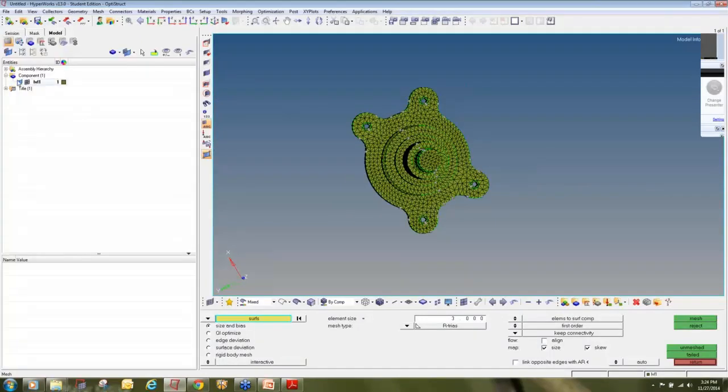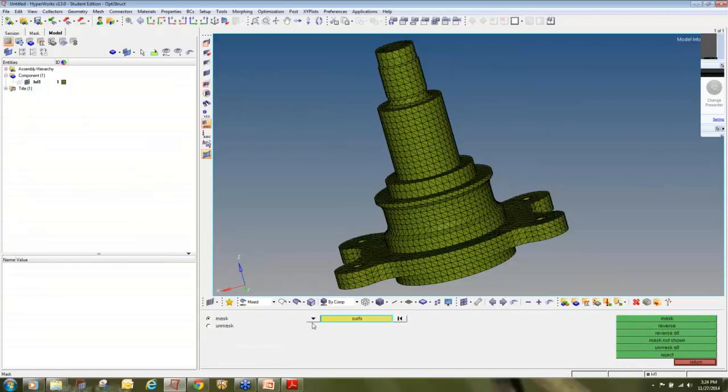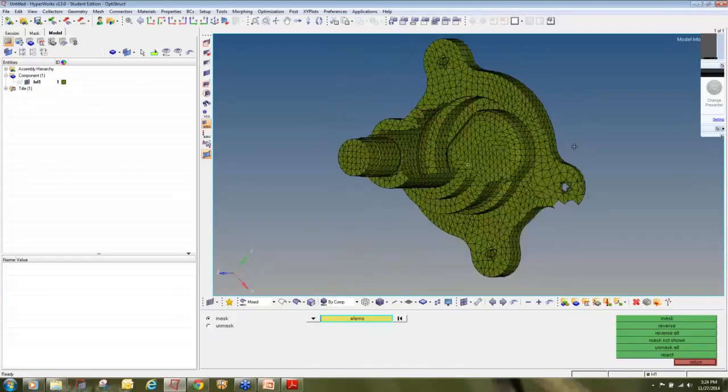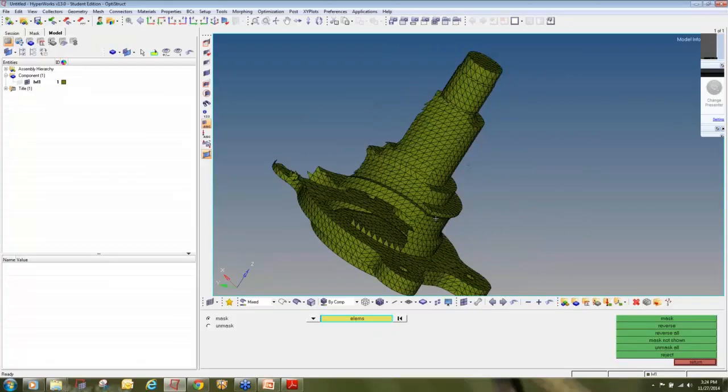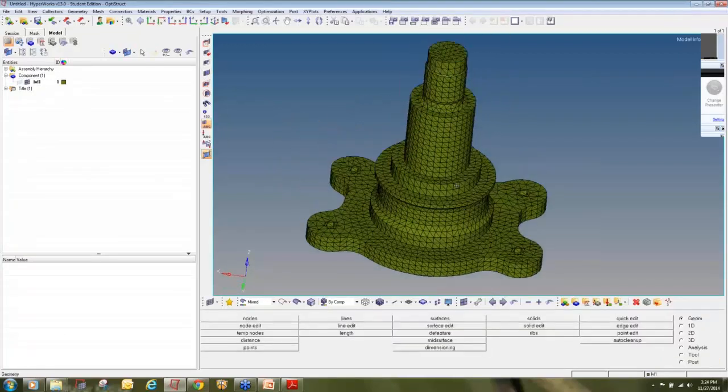So you can close this, go to model browser and off this. This is a 2D meshing. This meshing is also hollow from inside. I will show you. If I mask a portion, so this meshing is also hollow. We need to do a 3D solid meshing. So now the next step, till this time I have done 2D meshing. So the first step is to perform 2D meshing. Then the next step is to check the connectivity, whether these 2D elements are completely connected or not. As we already checked the connectivity of my geometry, 99.9% the elements will also be connected, but instead of assuming that these are connected, we will first check it whether they are connected or not.